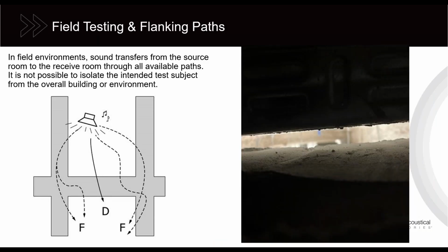So like I said, field testing is an important tool, but it's part of the factor. The photo here on the right came from one of our customers, noise barriers. They put in a very high performing door system, but when they got to the site, there was a big open gap where the wall met the ceiling, which was causing a flanking path around the door. So it didn't matter how well the door performed. The actual sound insulation between the two rooms was limited by this gap.